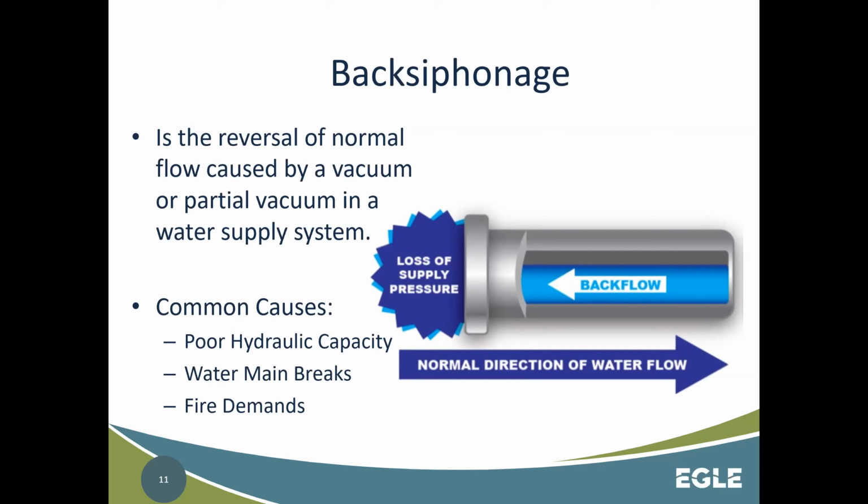What happens when a fire truck hooks to a fire hydrant? That is a great big vacuum on that truck, is it not? It's a pump sucking out water from the water system. Okay. So just so you know, during fire emergencies, the minimum residential pressure is not allowed to drop below 20 psi, but under fire emergency, minimum residential pressure for a water system can drop to 20 psi. All right.